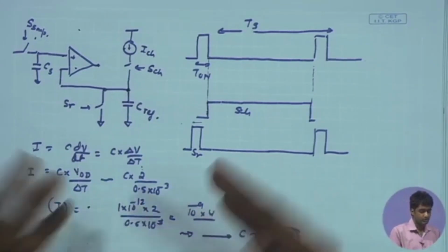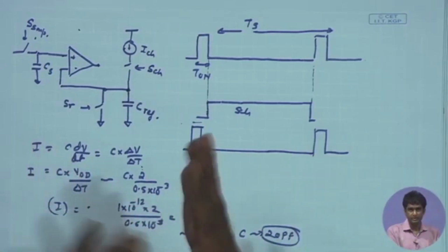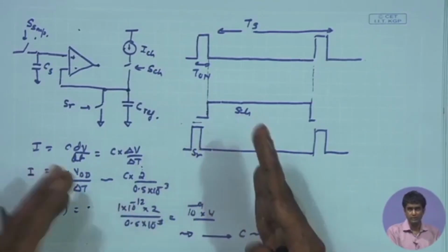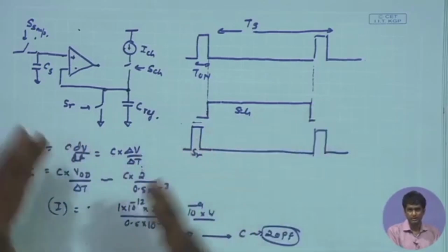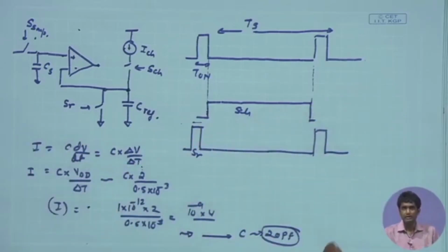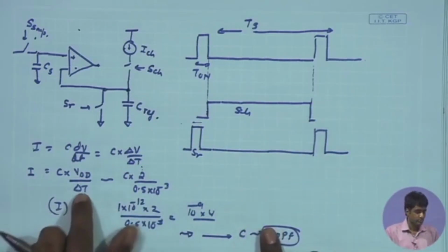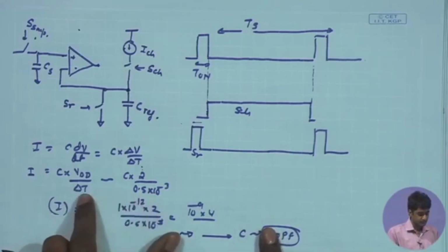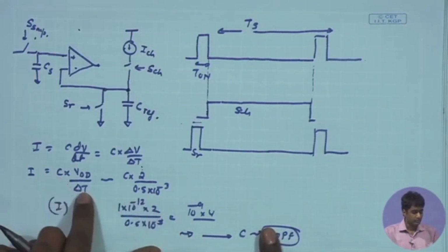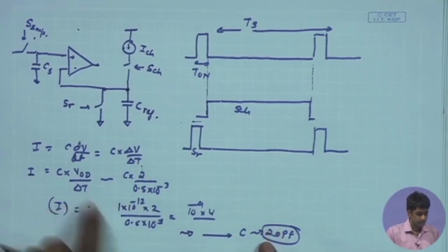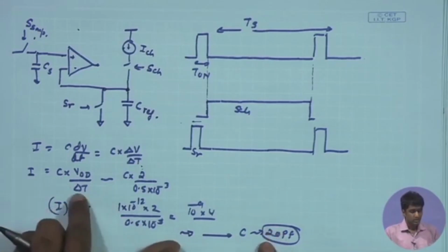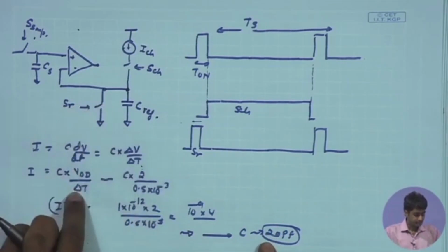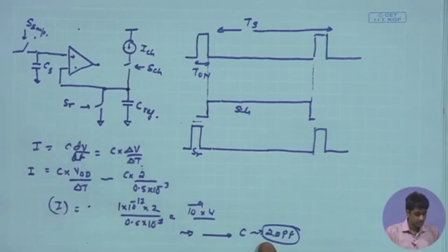So if I try to save power by curtailing my signal to a further lower frequency, rather than 1 kilohertz, if I try to curtail it to a few hundreds of hertz by using a low pass filter, then probably I will be able to use a larger T over here. I'm sorry.